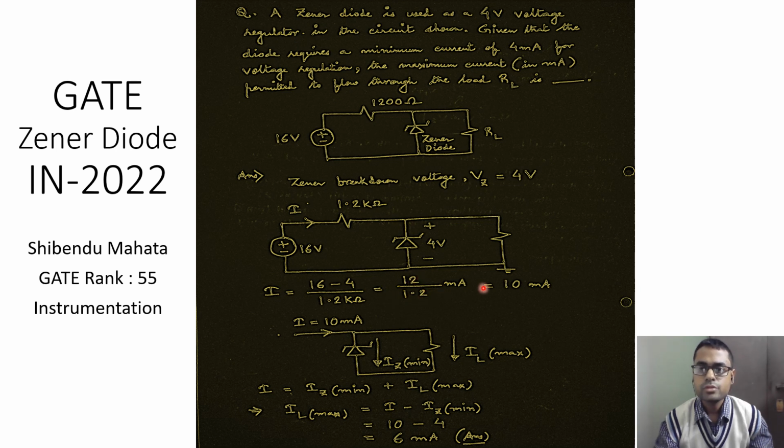There could be variations to this question where you can have a load resistance which is variable in nature, and then the question pattern will be: can you find out the range of variation of this load resistance for which the Zener still works in the reverse conduction mode, or for which you get voltage regulation. So in our next videos, we will look at those sort of questions.